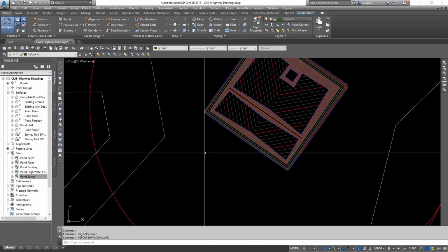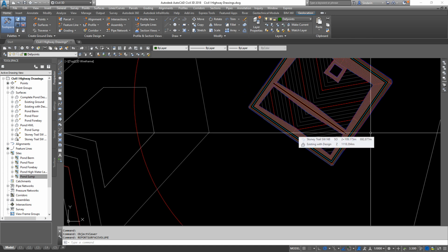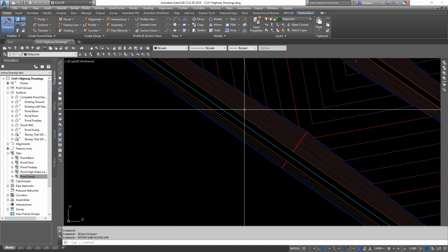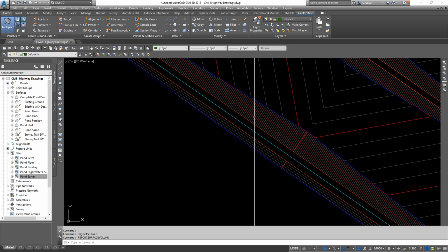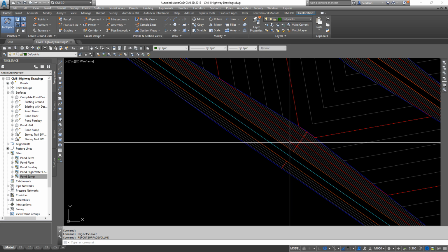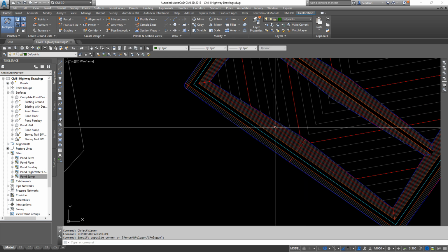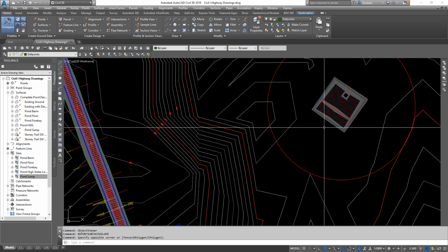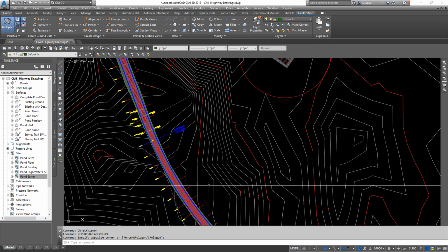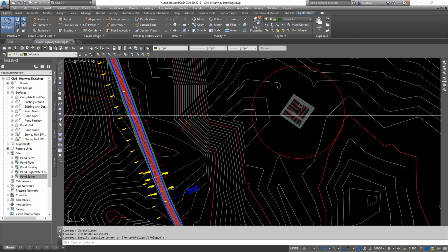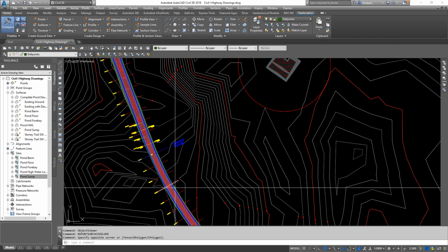If you want to take a step further, the exact same steps could be followed for a pond inlet. So choose the outside elevations, have a pond inlet the same elevation as your high water level, design a ditch to your road. Now, coming down the steep slope might not be the best idea, so come around over here.